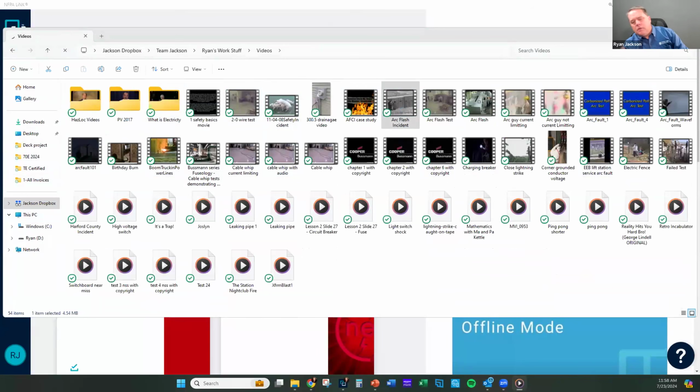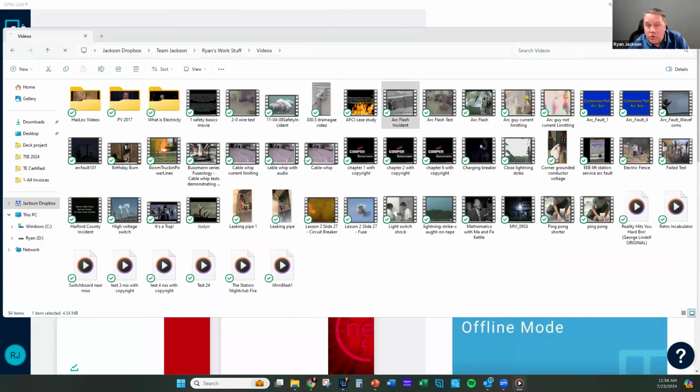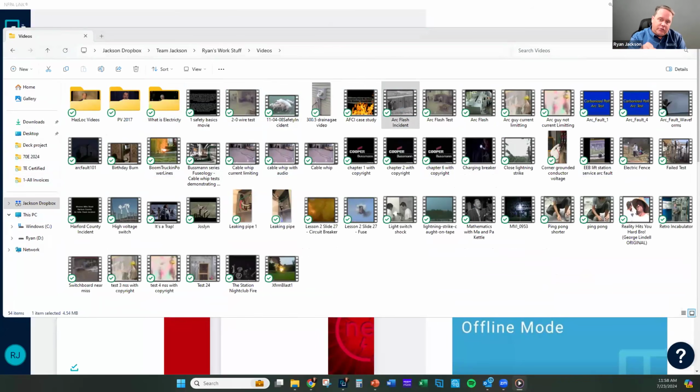So 3 people in this video are working on an emergency system switchboard. This is de-energized when this video starts, and a one in a million chance they are in this equipment, the utility power shuts off, the generator kicks on and turns on the equipment. So they didn't have the generator locked out, and that's what caused this.